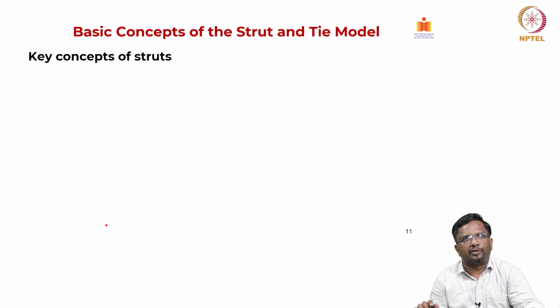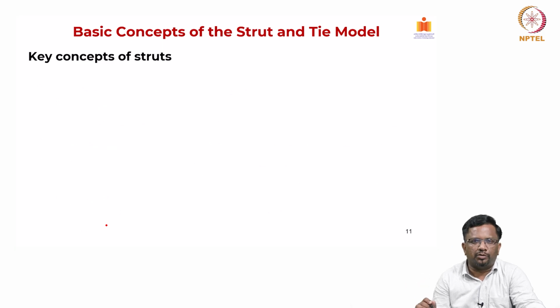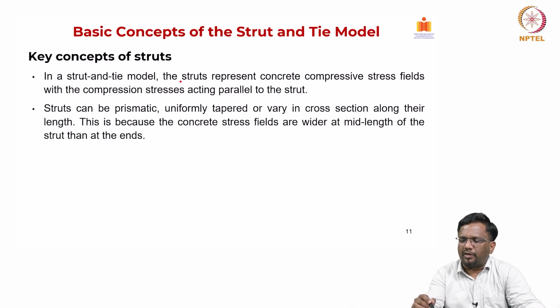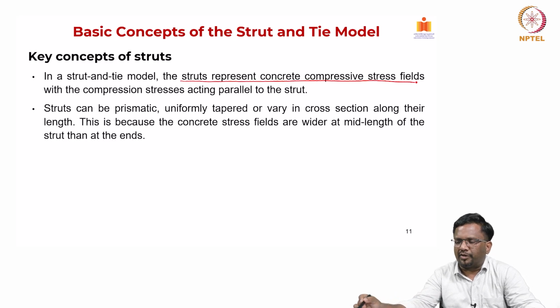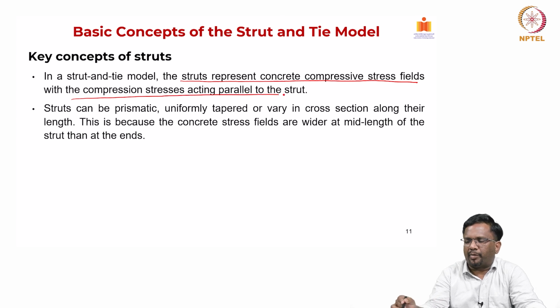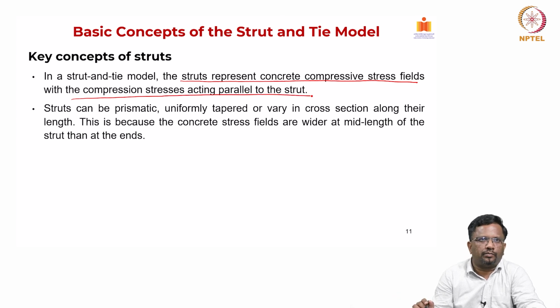Now, what are the key concepts of the struts? Let us look at all the individual components of the strut-and-tie model. What are the key concepts of struts? As you have seen, the struts represent the concrete compressive stress fields with the compressive stress acting parallel to the strut.